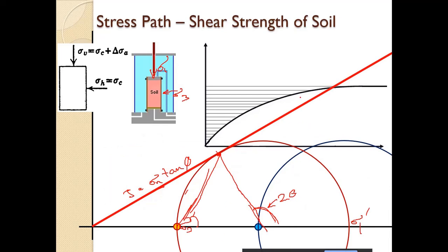soil will constantly deform and constantly shear at that particular value. It cannot take any more deviatoric load, and constant shearing at constant volume will occur if it has reached the critical void ratio state.